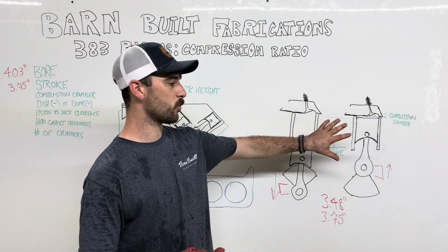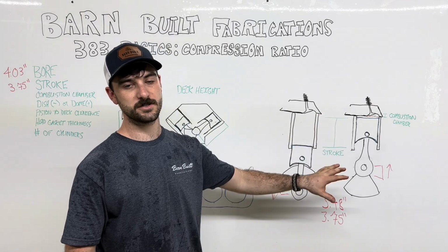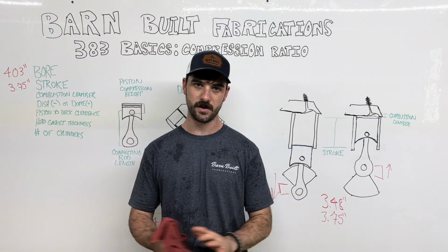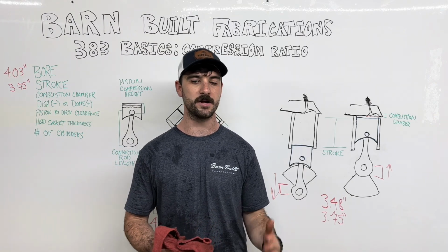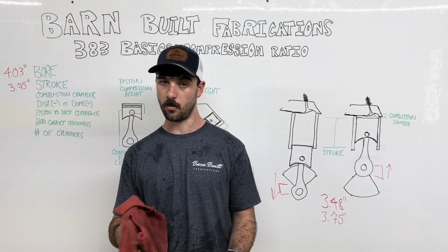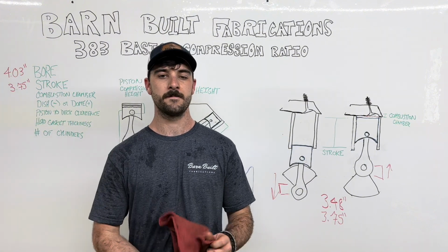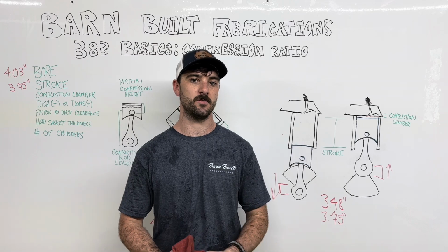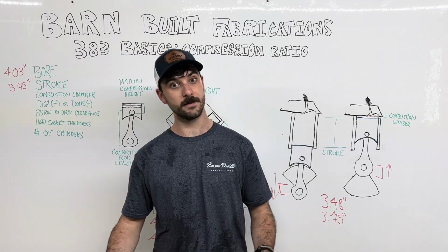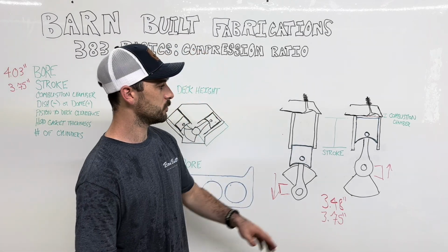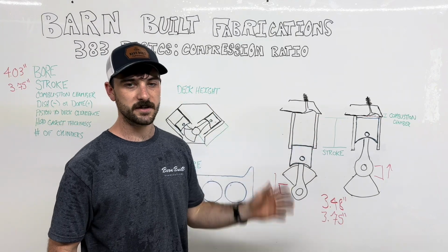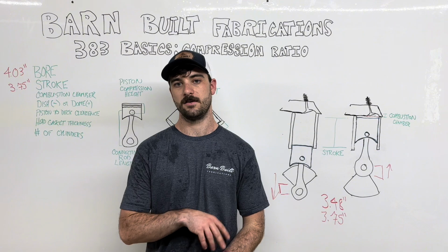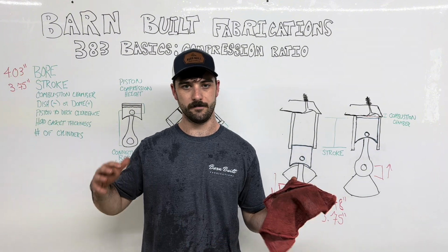So it is important to know what your compression ratio is when you're building it. That's honestly probably the biggest point of this whole thing. Too low of a compression, your engine won't run properly, or at all if it's low enough. And too high of a compression ratio, you'll run into detonation, which will cause mechanical failure, and then it won't run either.